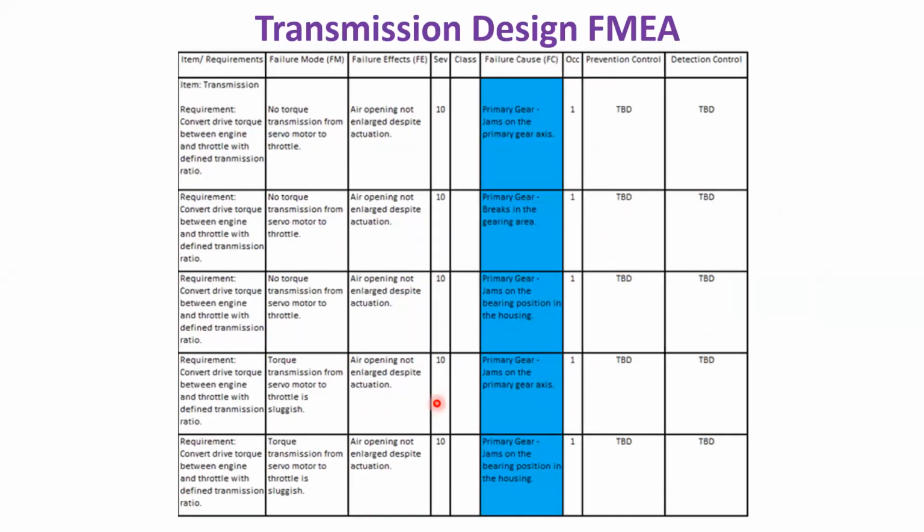But when it comes to a material or structural failure, it's very important that you can avoid all those things with the help of proper selection of design, where you follow the proper velocity ratio, gear ratio, law of gearing, and material selection with respect to grade 1, grade 2, what we have seen. Considering this, we can avoid those failures, and it is always better to follow the AGMA standard.